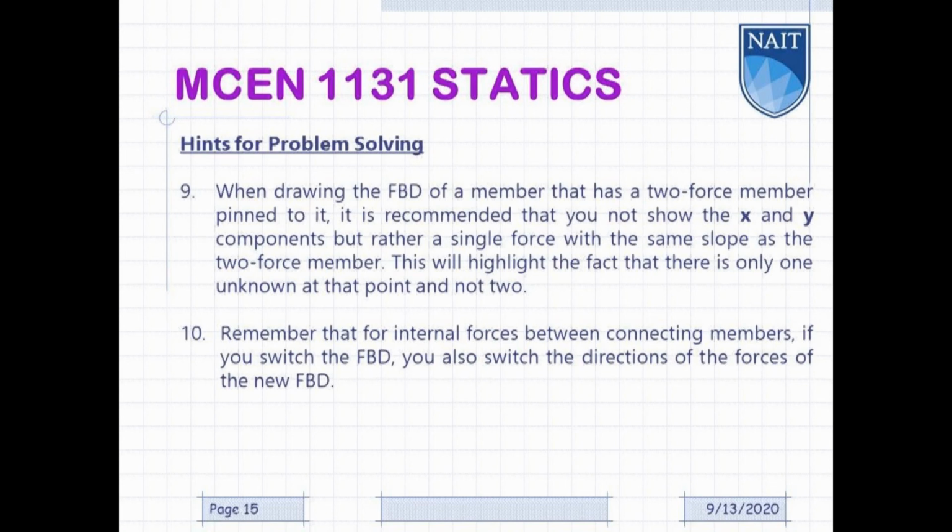9. When drawing the free body diagram of a member that has a two-force member pinned to it, it is recommended that you not show the X and Y components, but rather a single force with the same slope as the two-force member. This will highlight the fact that there is only one unknown at that point and not two. And 10. Remember that for internal forces between connecting members, if you switch the free body diagram, you also switch the direction of the forces of that new free body diagram.